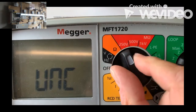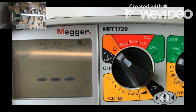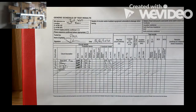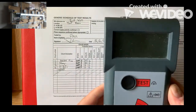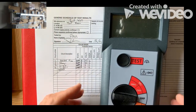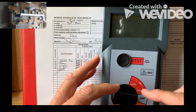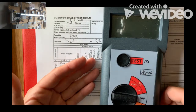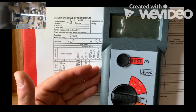It will have insulation resistance, but we could also use a simple tester that we started doing, which a lot of you have used, and it is basically an ohms tester. It does high and low, so it will do our insulation resistance and our continuity testing.